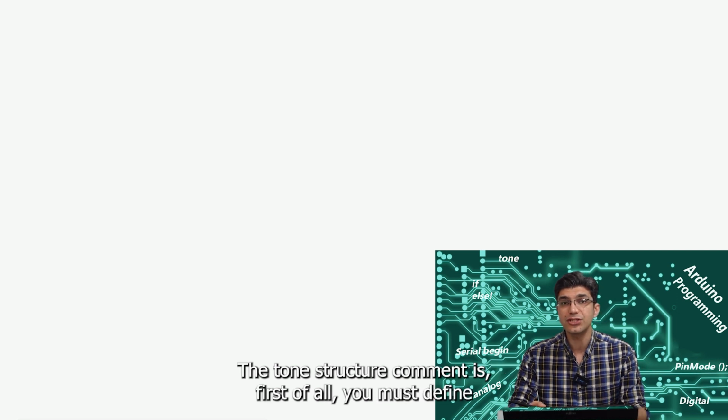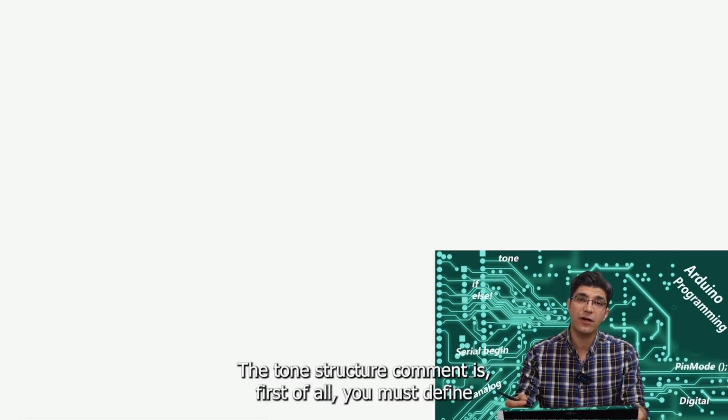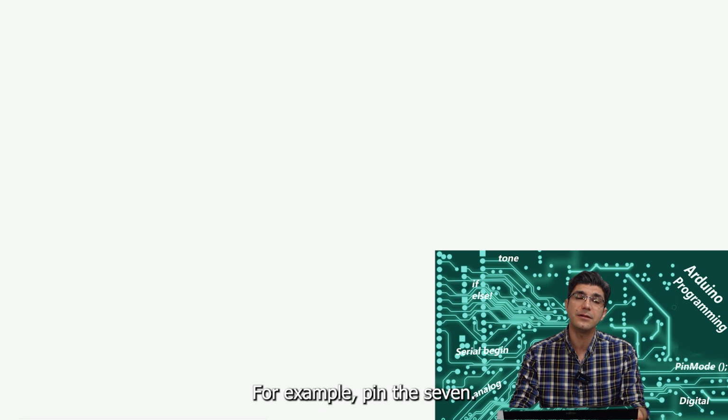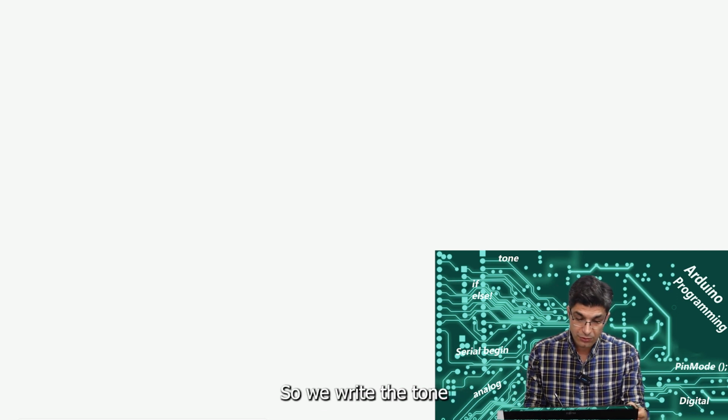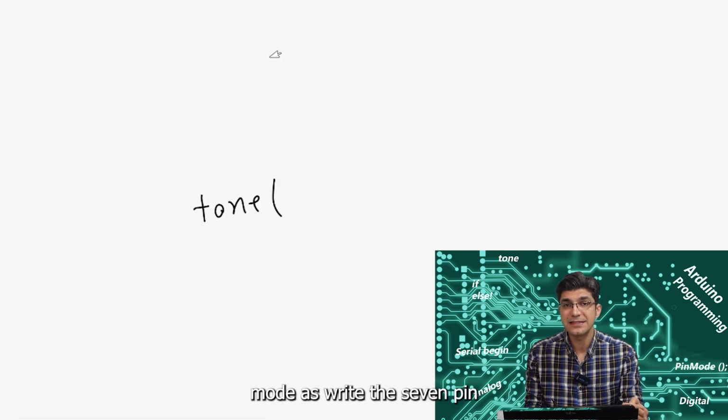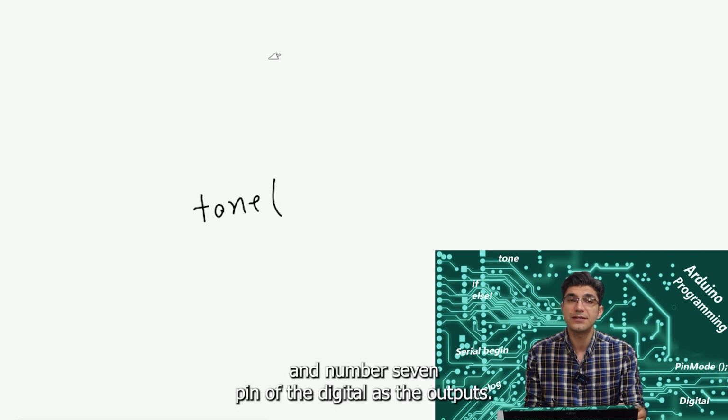The tone structure is, first of all, you must define one digital pin as an output. For example, pin 7. So we write pinMode with pin number 7, as the output.